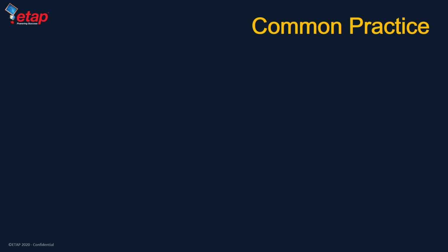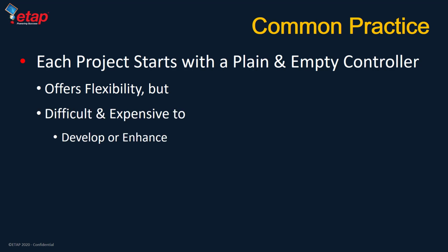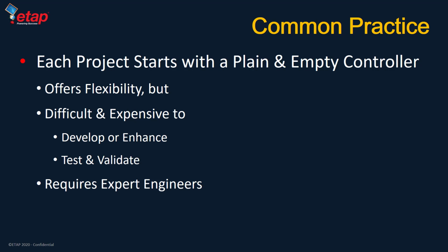One approach to implement microgrid controllers is to produce a generic controller. This approach offers flexibility to achieve desired control functionalities, although practically it may be limited to a certain level of control. In addition, this approach requires an engineering effort to develop and test the control functions for each microgrid project. Therefore, generic microgrid controllers may be limited to level 2 control and may not be suitable to implement level 3 functions such as economic dispatch.